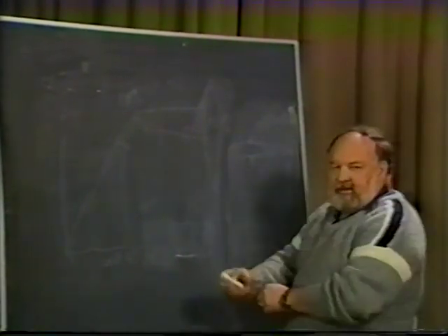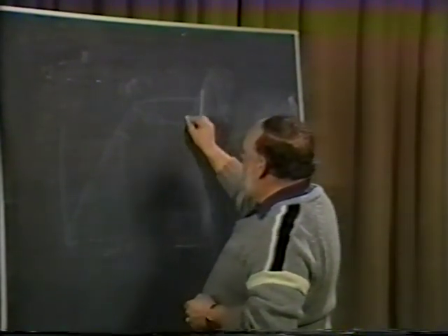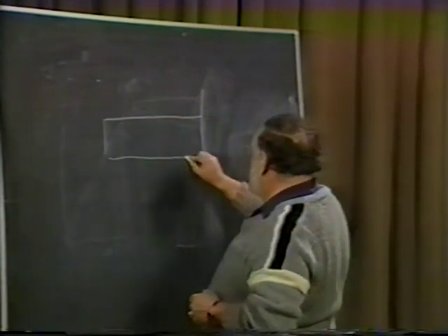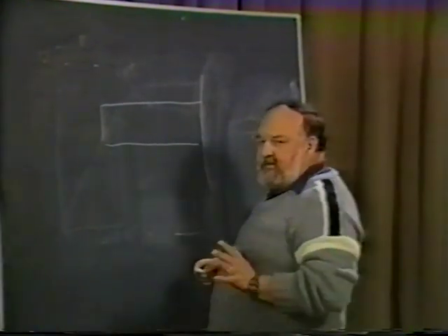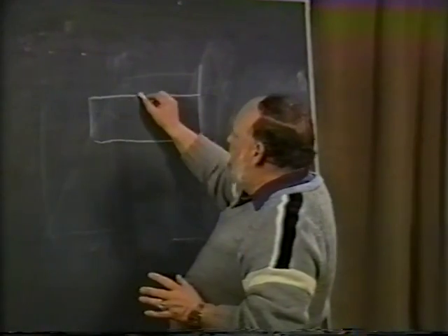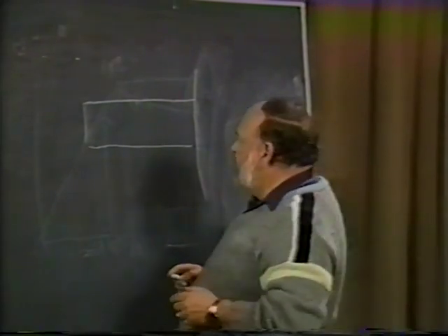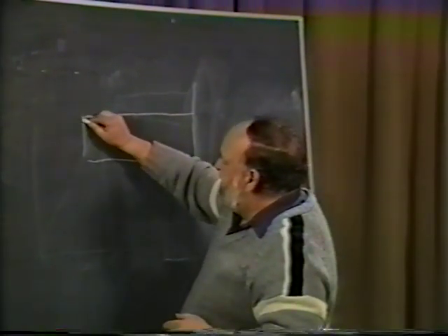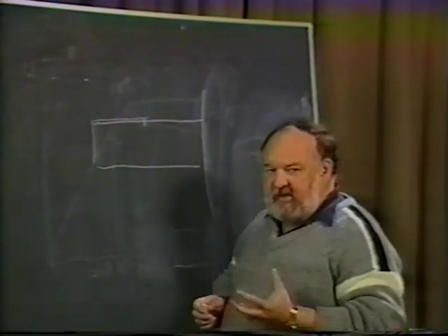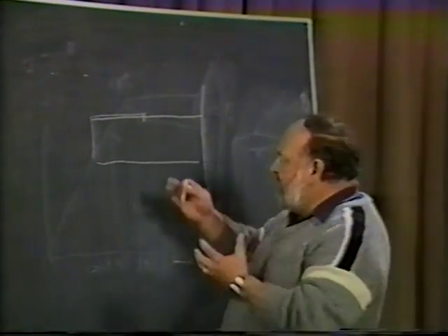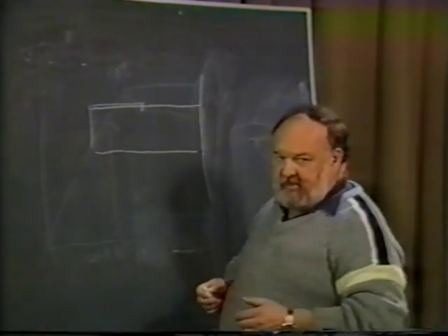NASA has been doing a fair amount of work recently in wing layouts. Let's in this case look at a more rectangular type of planform. And they have found that this outer half, at least the outer third, must be handled significantly in preventing that portion from stalling, whatever the method you want to use. One of the things they did, they put a cuff on here with a very large leading edge and actually drooped. And of course what that was doing is preventing the stall from occurring in the outboard section until quite a bit after what it would do in the inboard section.